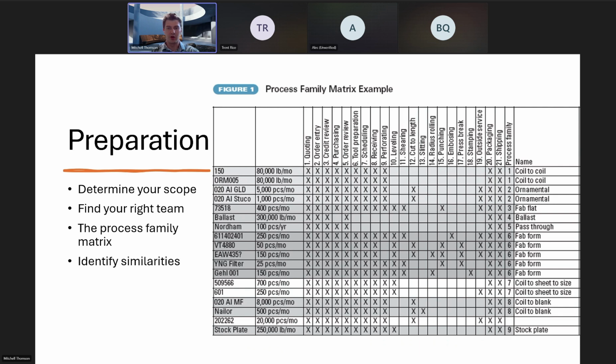Once you have that done for all parts and process steps, you can identify similarities, looking at process steps that have 100% overlapping components, and seeing if you can combine them, being same worker or related workstations. Then you can evaluate any workstations that have about 80% or above similarities and discuss with your team if you would like to investigate which one, depending on return on investment. So biggest improvements for least amount of dollars or work, greatest reduction in lead time, greatest impact to the customer, or most visible to shareholders.